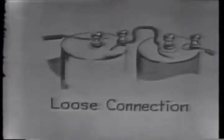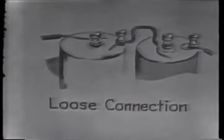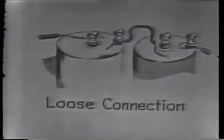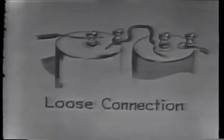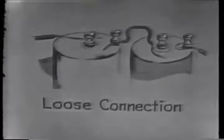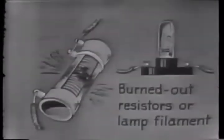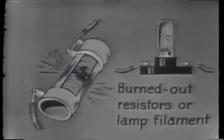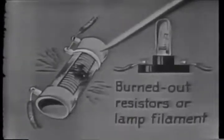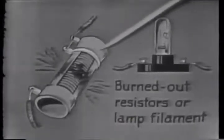Most of the time, a loose connection is the same as no connection, which is the same as an open. Any circuit component with a loose connection opens the circuit and stops current. Another type of trouble that will cause an open is a burned-out component. This is a burned-out resistor.